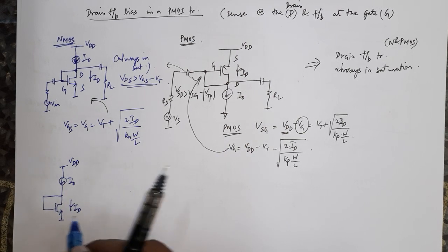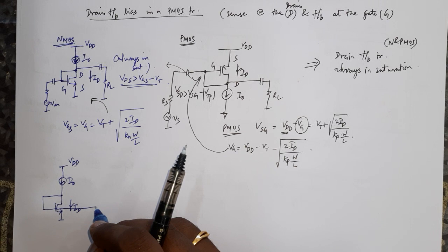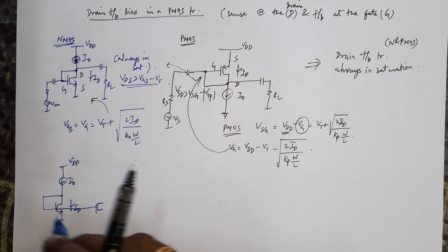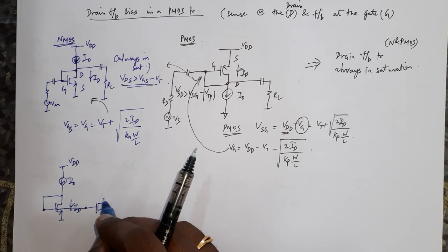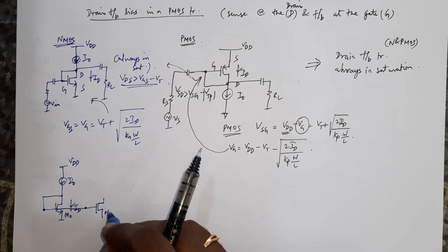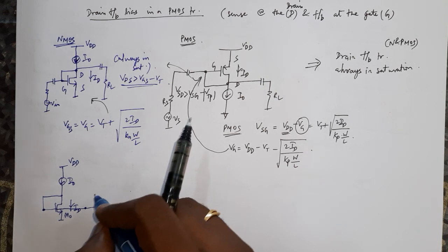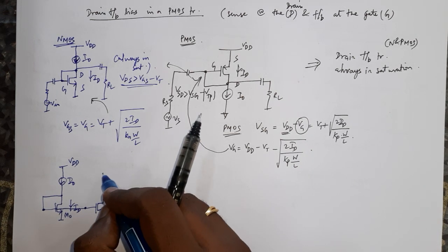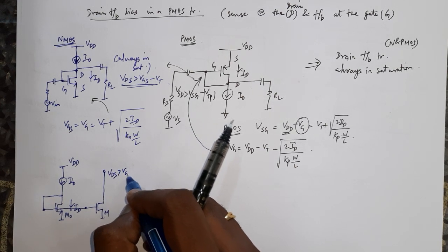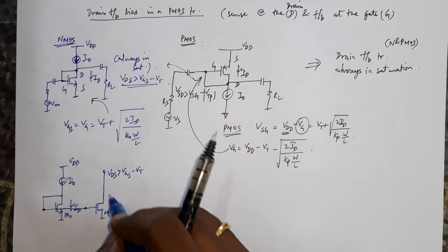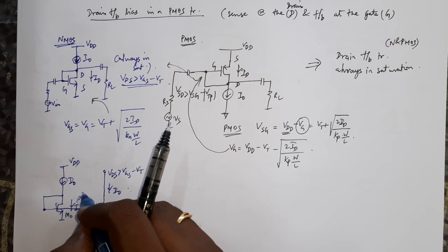Okay, if this is the case, then I can extend this particular gate voltage to other gates so that this voltage and this voltage are the same, and if these transistors M0 and M1 are exactly matched, then as long as I keep my VDS greater than VGS minus VT, I'll have a current that flows here equal to I0, because this also equals I0.